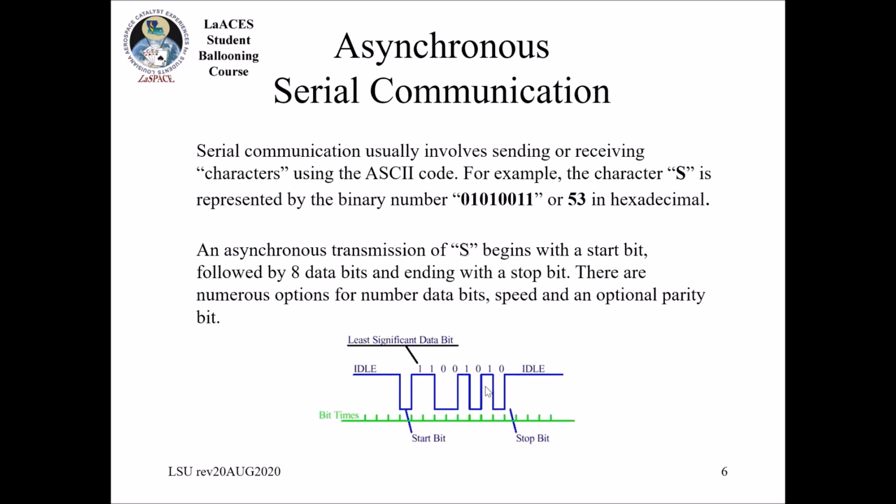You can see that, in this particular instance, because this is the time axis, it has transmitted the most significant bit first, and then it's transmitting the least significant bit last. It's very important to know this, but for the built-in functions, like what we're going to be using for the I2C bus, it's going to do all of this for you internally, because there's a standard for I2C that the people that design these systems know, and so they always use that standard.